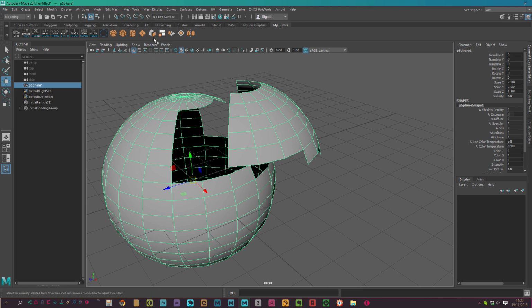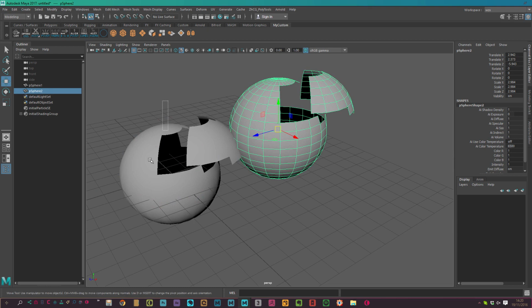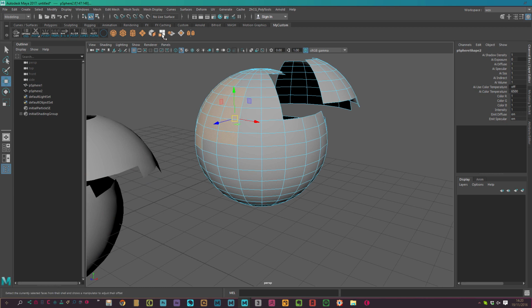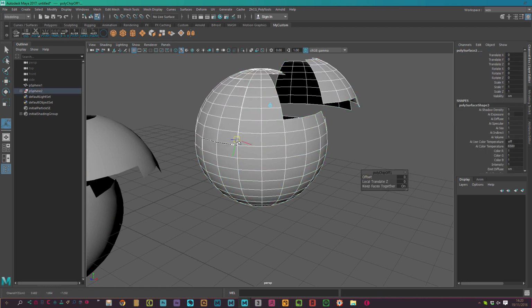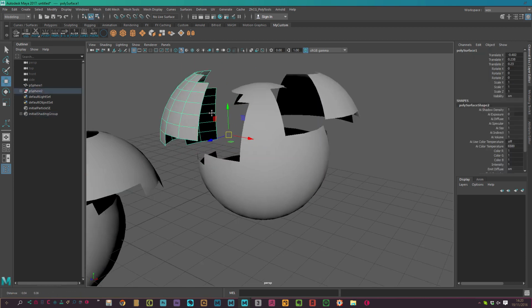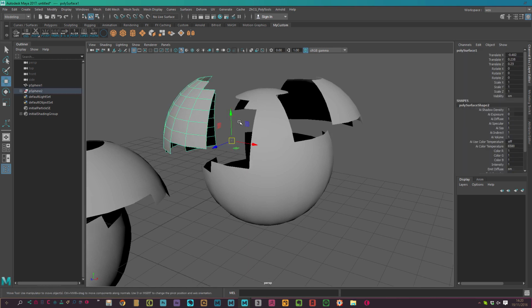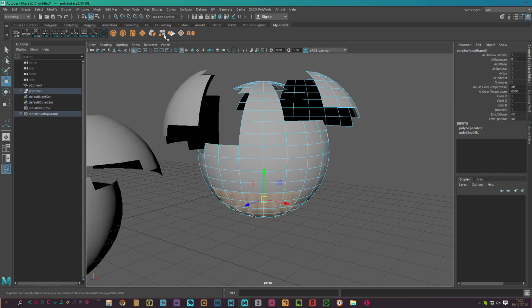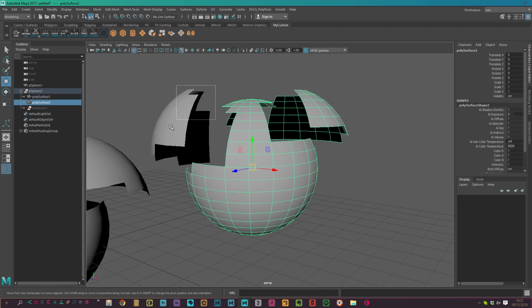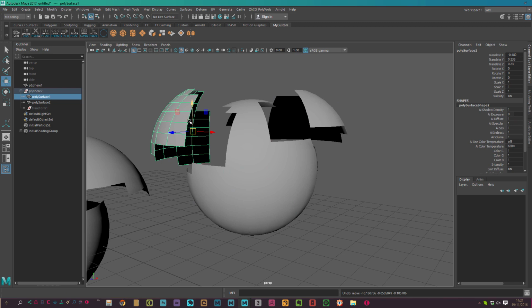Here, the difference between these two is that this one extracts in the same shape, but the second one will extract, if I select, in a new shape. The problem is that when you do that, it doesn't come back in object mode, it keeps on transform mode. It's boring because we need to switch into object mode, and you have history, and you have no center axis here. You see, I need to manually center my axis.